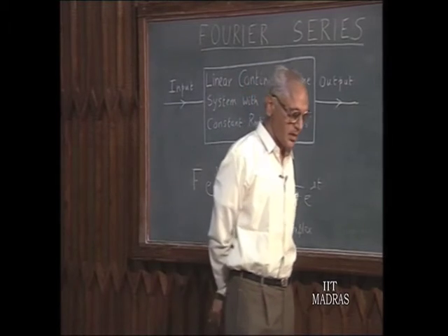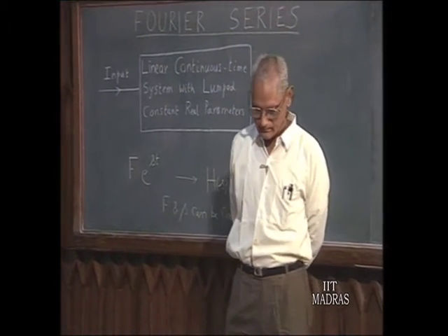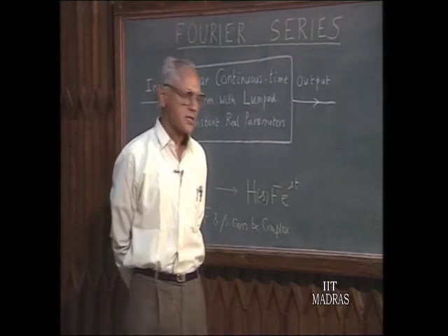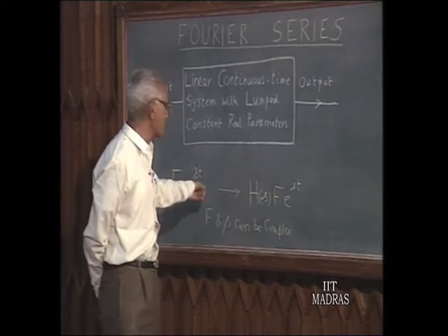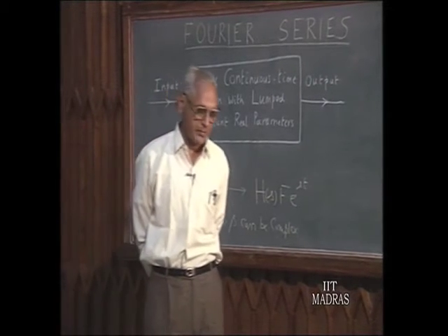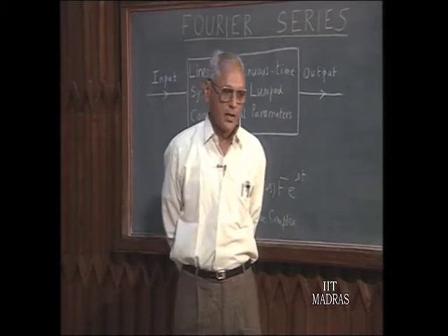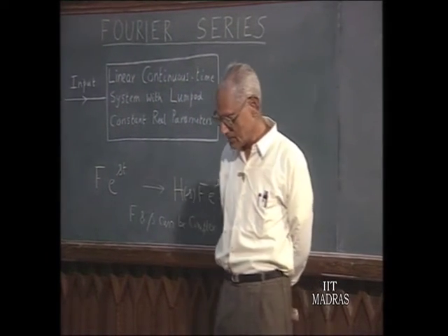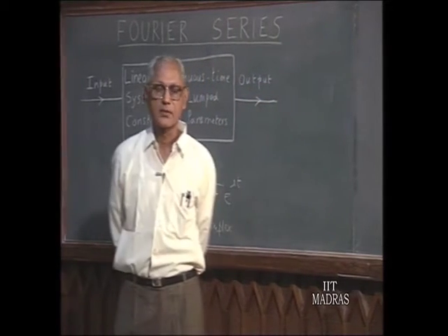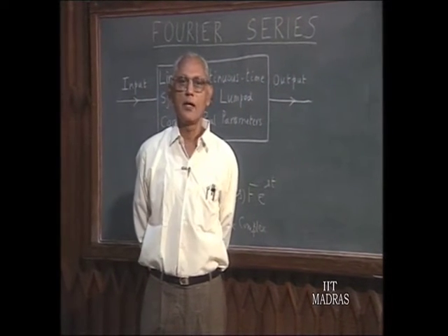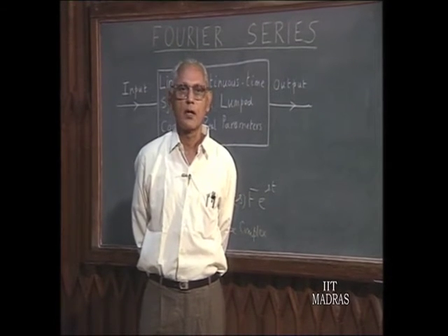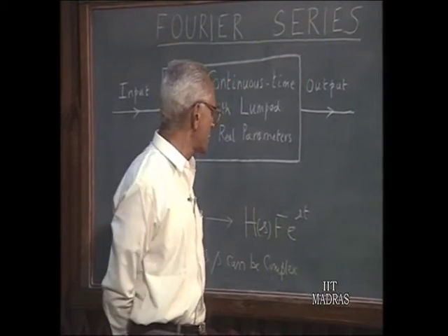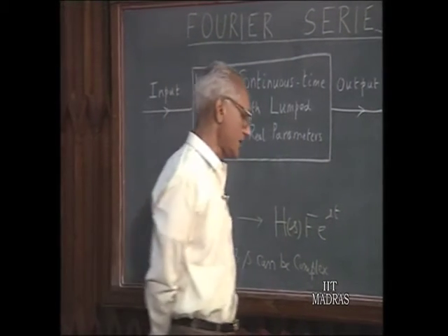However, the sinusoidal function of time, which plays such a vital role in AC circuit analysis, is a very close relative of an exponential signal e to the power of s t, as we will see presently. Therefore, we would like now to see how to relate this exponential signal e to the power of s t with the sinusoidal signal, and if the sinusoidal signal is the input, how we can obtain the output in terms of this h of s. So, let us see how it goes.